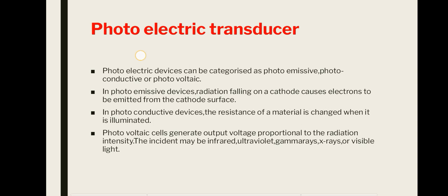Amplification of the original current by as much as 10^5 to 10^9 is common. Luminous sensitivities range from 1 ampere per lumen or less to over 2000 amperes per lumen. Typical anode current ratings range from a minimum of 100 microamps to a maximum of 1 milliamp. The extreme luminous sensitivity possible with these devices is such that for a sensitivity of 100 amps per lumen, only 10^-5 lumen is needed to produce 1 milliamp of output current.